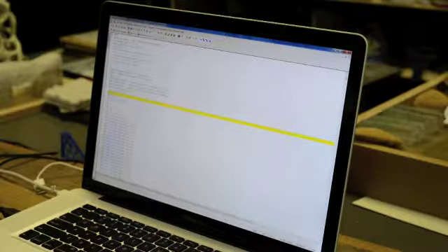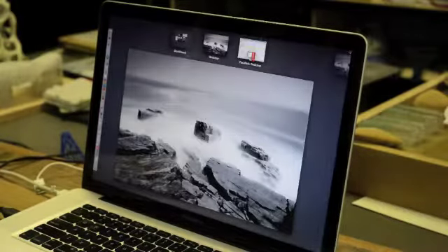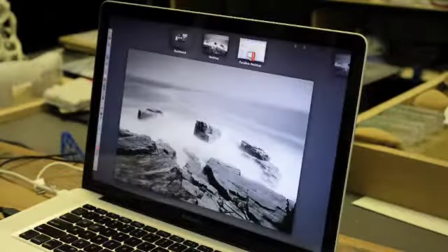And one troubleshooting issue: sometimes if you're downstairs running the mill and you get an error that says like X-axis out of bounds, for example, it's usually because your shift is a negative value, or just a huge value because you typed like 12,000 instead of 120, for example. So that's the first place I would go to check if you had an out of bounds error. So you just close that out.